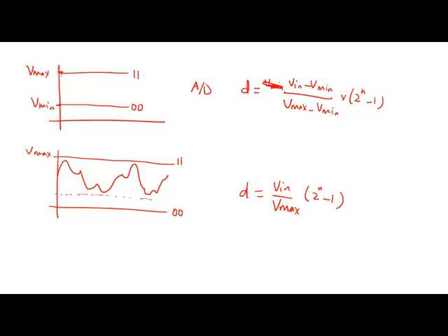And now, here's going to be the difference. The resolution here is going to be this whole range from Vmax to 0 divided into equal segments, so your resolution is Vmax divided by 1023. But here you're saying, no, don't go all the way down.